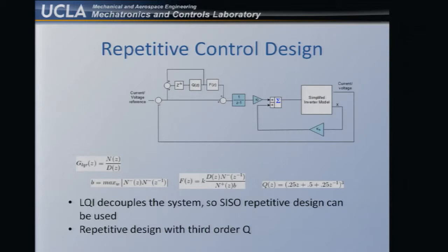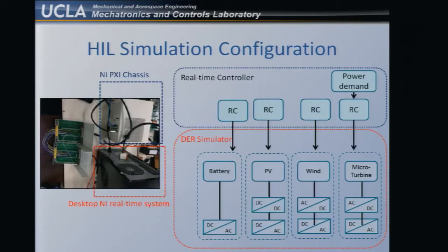It just needs a little bit more memory for the delay buffers. But the effect is that it's able to track, in principle, all the Fourier harmonics of the basic frequency, say 60 hertz, okay? In practice, it can do maybe 10 to 20 harmonics instead of all the Fourier harmonics. Okay, and I won't get into how the control is designed, but I would like to show you the results.